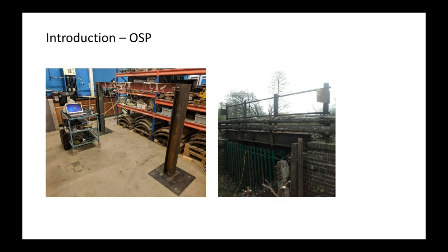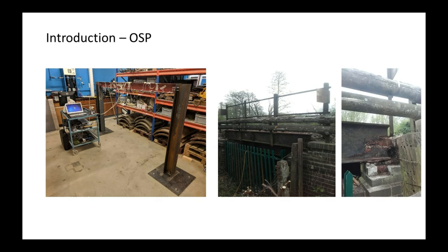Due to weathering, it cracks and water goes into the brick masonry, so it corrodes. If you see, the ends become thinner. There are big holes at the ends. To monitor them, they need to break the end blocks. Whether there is damage or no damage, they have to break it to check it. So they wanted to avoid that. They said, could you identify the holes, something like this, without breaking the end blocks?